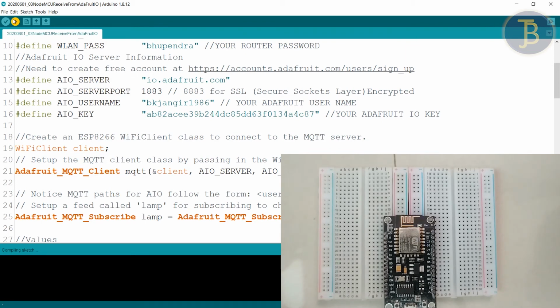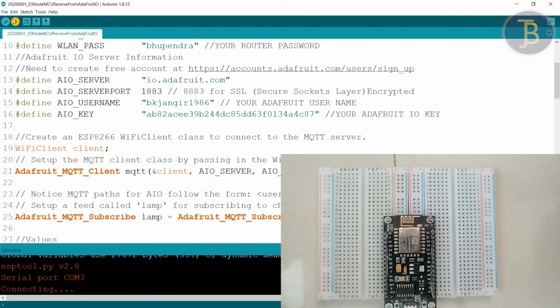We have not connected the circuit diagram till this point, and always be careful in this case, and do not use USB power unless you have a load of only an LED. In case of an LED we can use the USB power, otherwise we have to go with adapter power to supply the board. Done uploading.